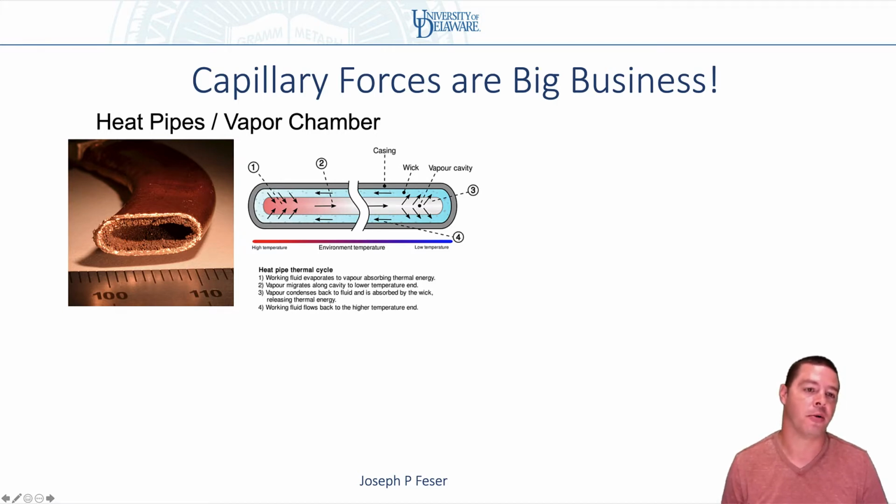The way they work, for example, is that you can think about them like a cooling system where you are boiling off water in one location, and you have basically a hollow tube that's surrounded by porous material on the outside of the hollow tube. After you boil the water or whatever fluids in the heat pipe, it is able to travel down the center of that hollow pipe and then condense somewhere else where it's cold. But then you need to be able to get the fluid to go back to the boiling area so that you can repeat the cycle. And that's where porous materials come in.